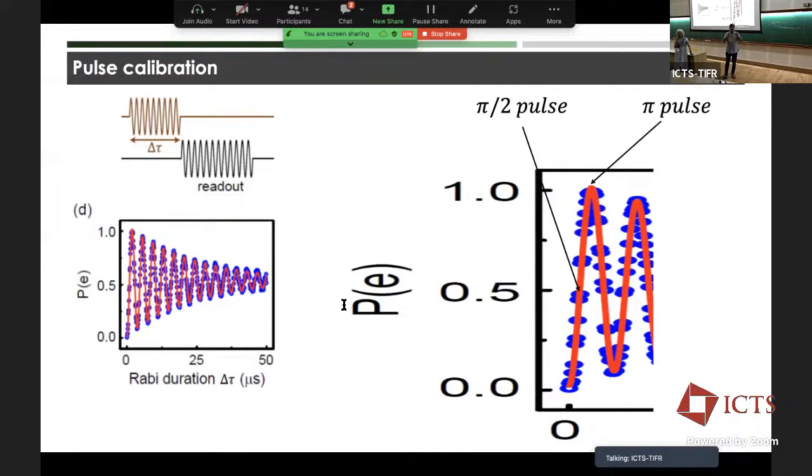These kinds of things we refer to as two-level systems because they have two configurations, and that can happen due to defects in the crystal structure or the actual structure of atoms. That change of position affects the dielectric constant of the capacitor because now the electric fields are slightly different in the two configurations. And capacitance translates to a frequency change, and that frequency change translates to dephasing noise, right? So this is an example of that.